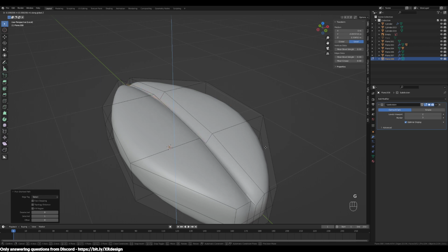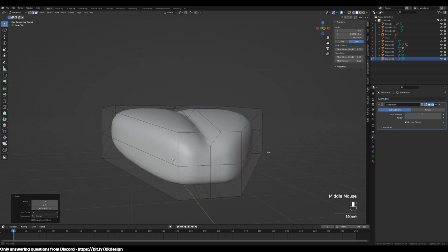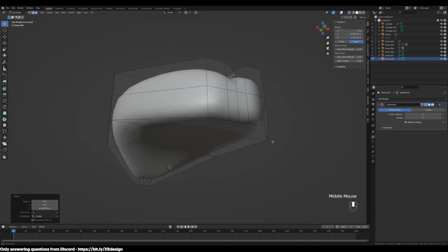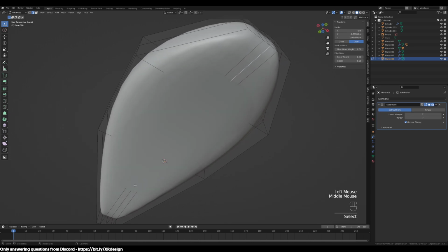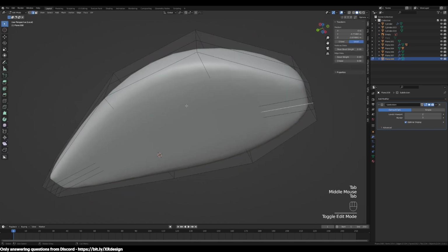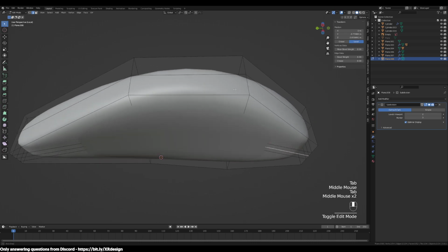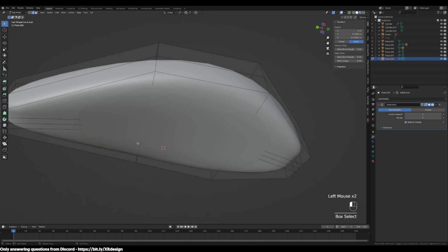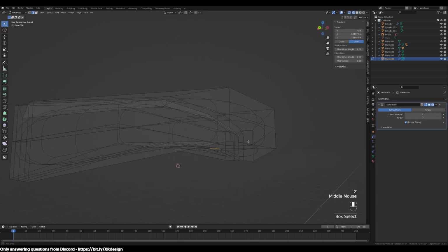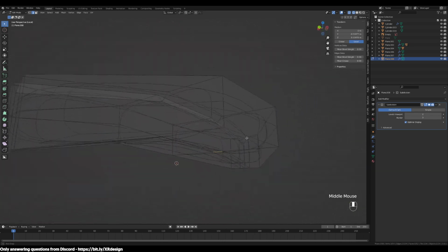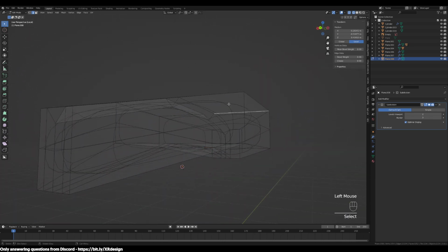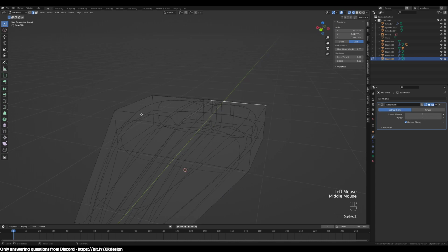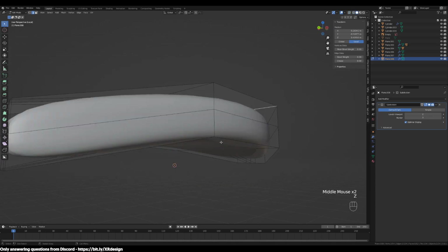So I'm just gonna lower this top face here. Maybe I'll lower the bottom too. So because of the subdivision, you can't see the base model of the bottom. You won't be seeing these edges here. So you can either go to wireframe view, which is a little bit more confusing in my opinion, because you're seeing both the base object and the subdivision model.